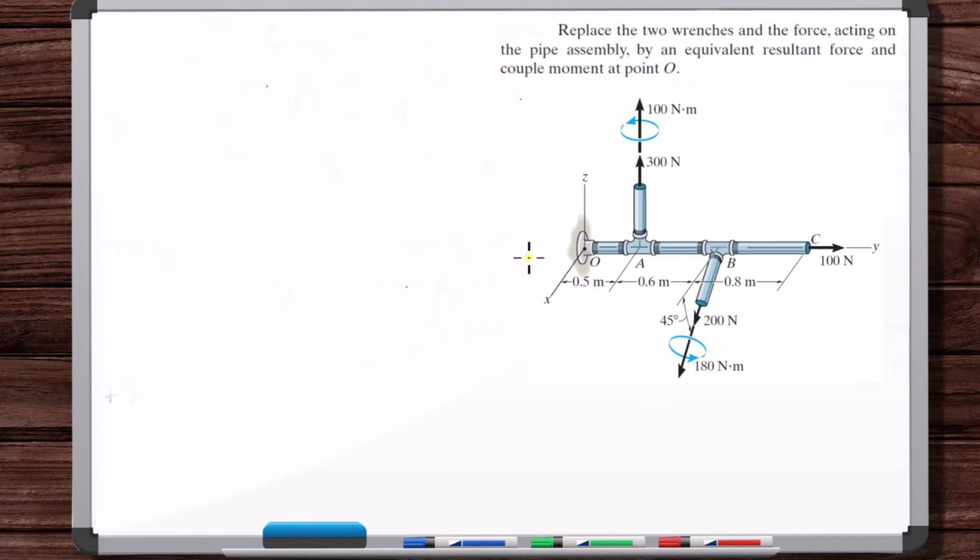Well, for the most general case of a force couple system, so in 3D, forces, couples, whatever, in random directions, a wrench is the most you can simplify a general system. In some of the previous example problems, we've done special cases, like a coplanar force system or parallel force system or concurrent force system. Those you can simplify even more than a wrench. A wrench is at a single point, you have a force and couple moment at the same point, and also in the same direction.